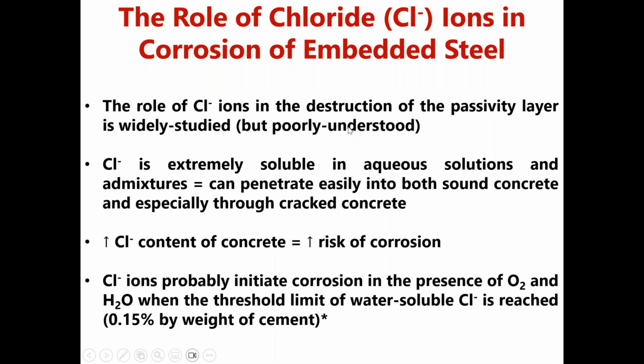The problem is we know that chlorides play a big role. Chloride plays a big role in the breakdown of the passivity layer of embedded steel and initiates corrosion and oxidation of the embedded steel. We know that's the case. The more chloride there is, the higher the risk of corrosion. We also understand that chloride is, like I mentioned before, highly soluble, so it's easily introduced into the concrete.